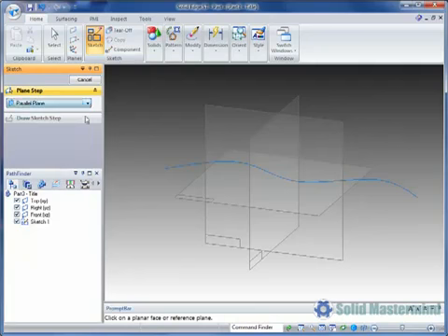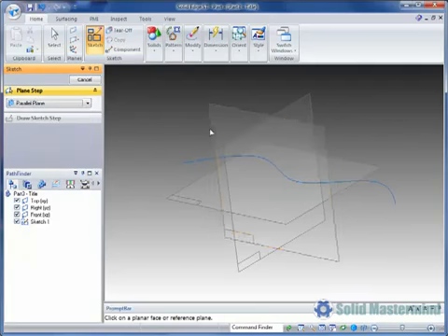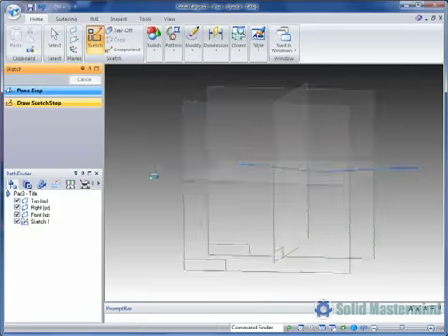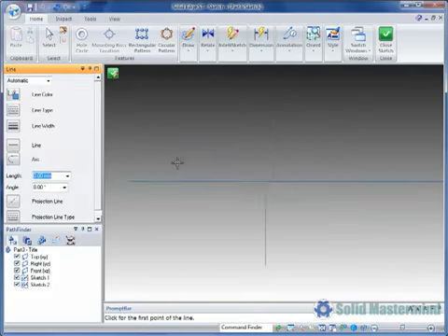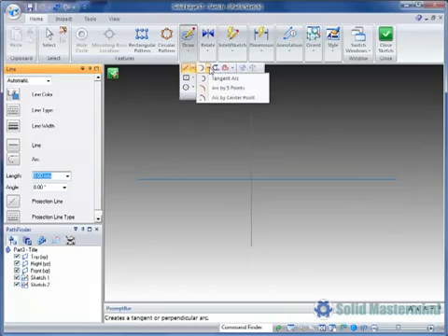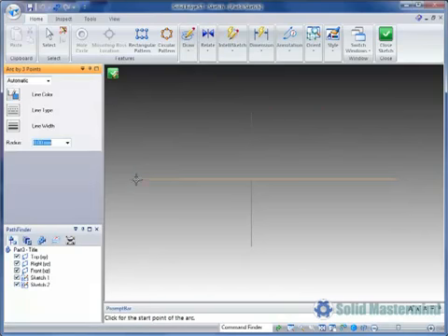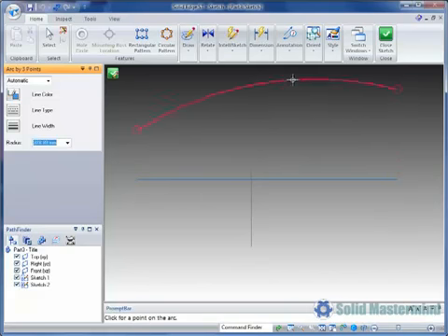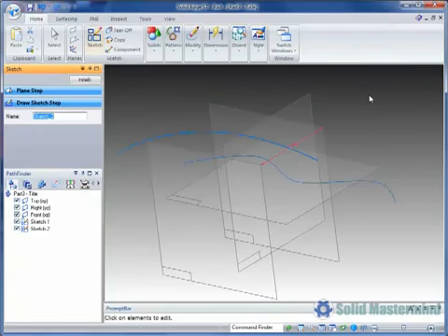We'll then create another sketch and use the parallel plane option. Identify the front reference plane and set the distance towards the left-hand side. Once in the sketch, we'll draw a 3-point arc. We'll make sure the start and end of the arc are lined up with the ends of the curve that was in the first sketch. And then finish.